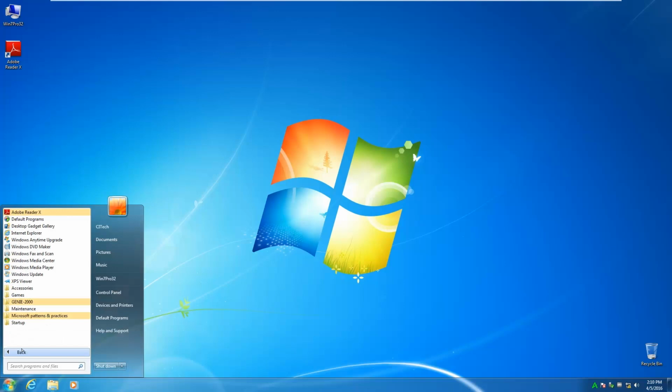This happens automatically if the new MCA input definition is created and saved using the MID Setup Wizard. When using the MCA Input Definition Editor program instead of the MID Setup Wizard, a new MCA input definition must be manually loaded into the Runtime Configuration Database before it can be used, and it must be manually unloaded from the database before it can be edited or deleted.